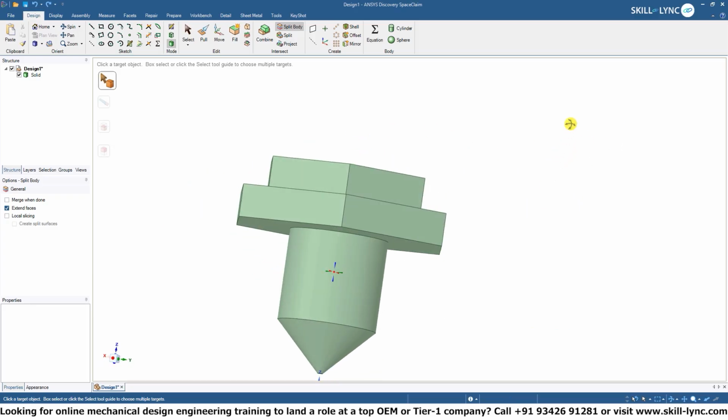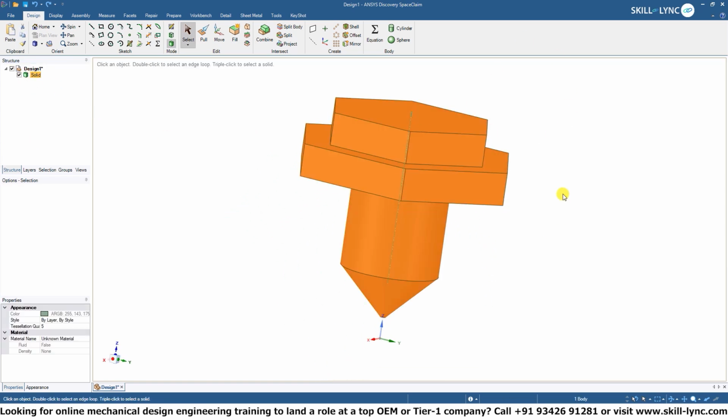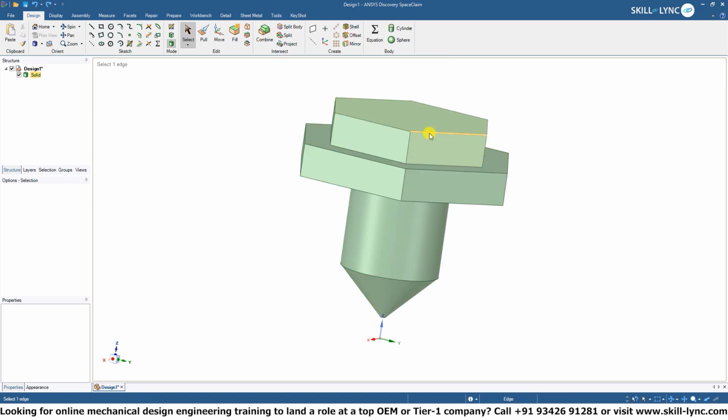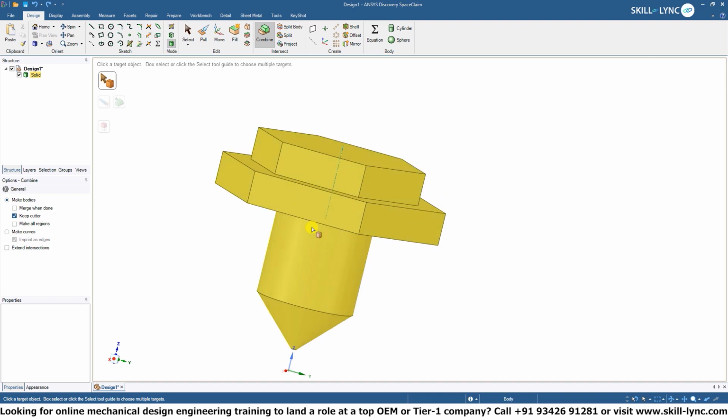One more technique that I'd like to discuss is, obviously, we looked up to now at how we can create a solid body or an assembly of bodies, and how we can use the combine tool. Obviously, it was a bit difficult to use the combine tool itself to split this body without creating additional geometry. What I was struggling with a few minutes ago was trying to select this surface area to actually split the body, but it wasn't allowing me to create that selection. And that's because I wasn't using the correct tool in the intersect property.